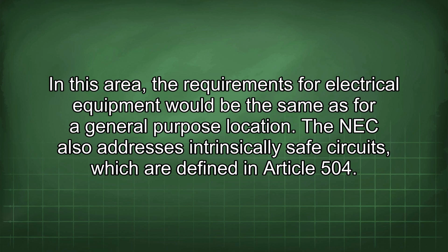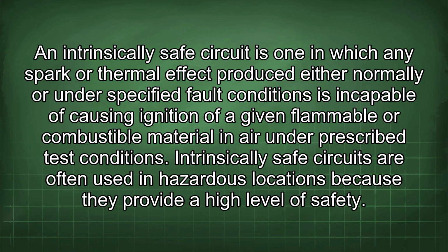The NEC also addresses intrinsically safe circuits, which are defined in Article 504. An intrinsically safe circuit is one in which any spark or thermal effect produced either normally or under specified fault conditions is incapable of causing ignition of a given flammable or combustible material in air under prescribed test conditions.